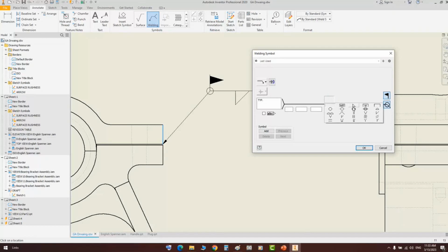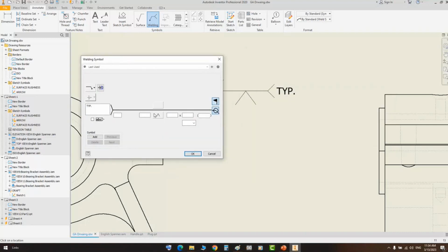If you would like to add another option for welding, you just select the sample from here to there. If it's a groove weld like that, or it's two surfaces, radius surfaces like that, or a groove weld or a fillet weld. So you can select the option, and you can add a top character here to indicate the end of the fillet weld. It's at top or bottom or flushed or faced like that.